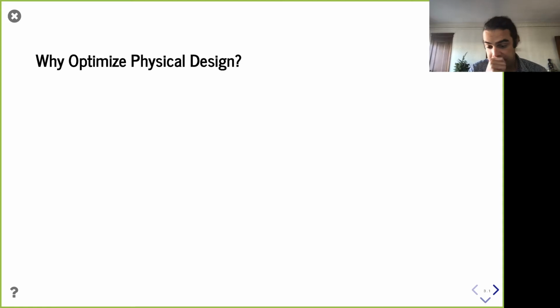So let's remind ourselves where things fit in here. We've been talking a lot about hardware design, and so far we've been writing Chisel, and it runs in a simulator, and we design hardware, but at this point it's almost just the specification. Chisel is just a description of the cycle level behavior of your design, but it's not implemented. It's not turned into something like an FPGA. It's not turned into a chip. So the process of making that real is physical design, in particular for an ASIC, making an actual compute chip is that process.